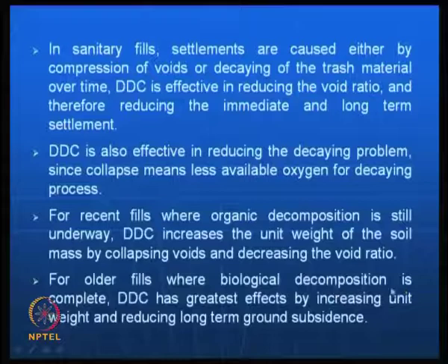In the case of compacted samples, like an embankment, you have to expect settlements of the order of 0.1% of the total height. Here the settlements could be very high, 10%, because of the biodegradable matter being present. So definitely dynamic compaction is very helpful in reducing the settlements, and in some places where the fills are old and biological decomposition is complete, dynamic compaction is very useful in increasing the unit weight and in reducing the long term subsidence. This is another important point.